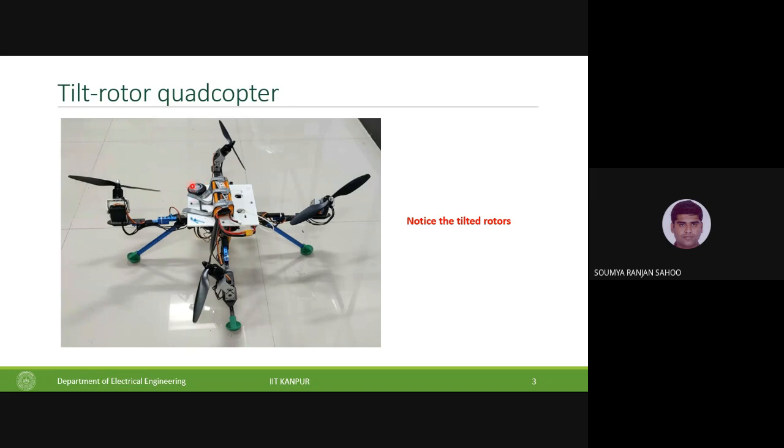You see this black module here, this is the GPS module with the magnetometer in it, and it is pointing in the forward direction. So this is my x-axis that I have set up. I want my quad to survey a structure while moving from left to right with the x-axis pointing towards the structure. So the structure is right in front of my quad and I want to survey it horizontally, so I need to have a lateral motion.